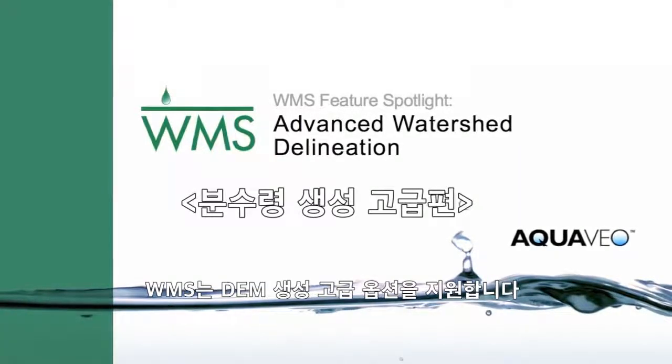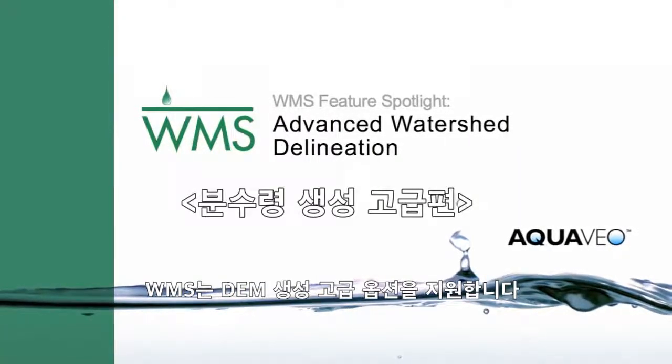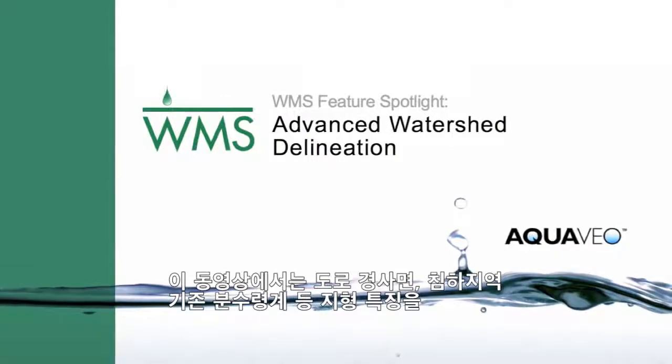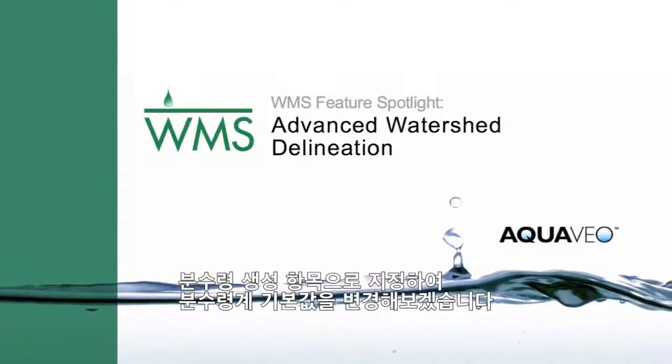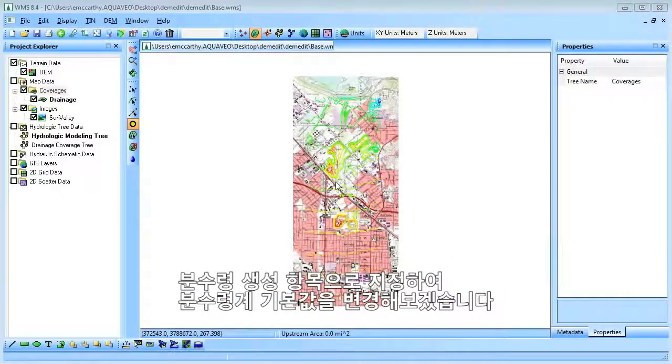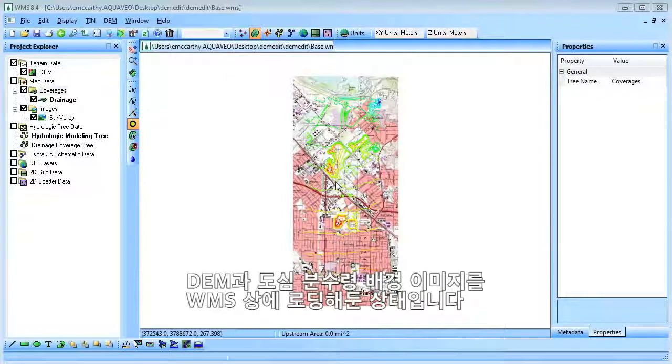WMS supports advanced DEM delineation options. In this video, we will manipulate the default watershed boundaries by assigning map features such as road embankments, depressions, and known watershed boundaries to watershed delineations. A DEM and background image for an urban watershed have already been loaded into WMS.